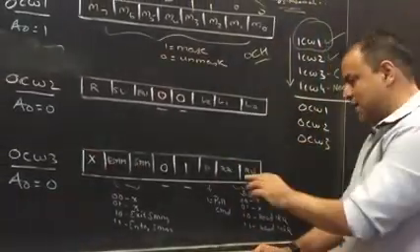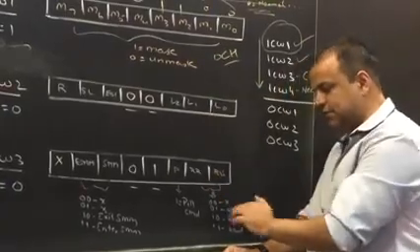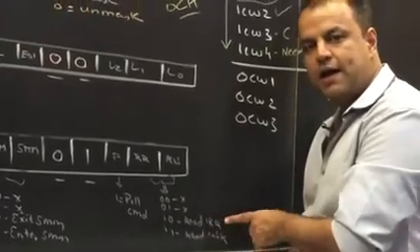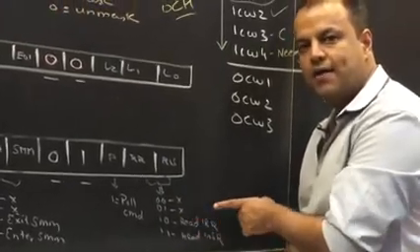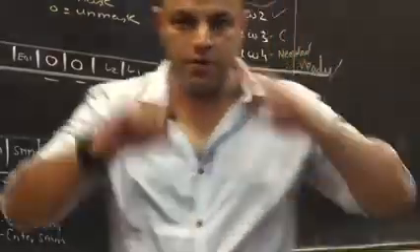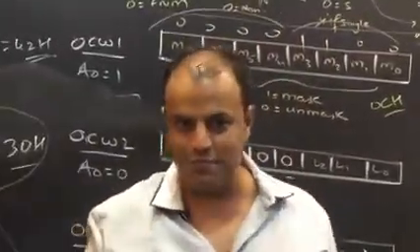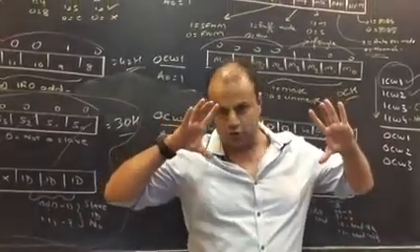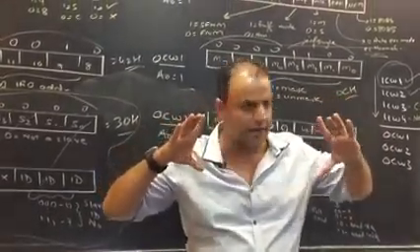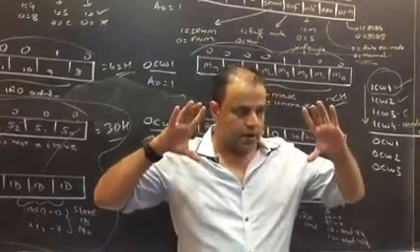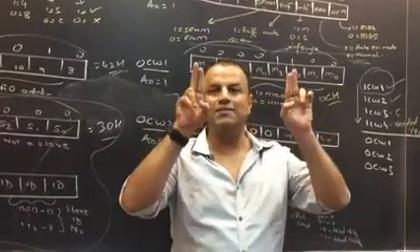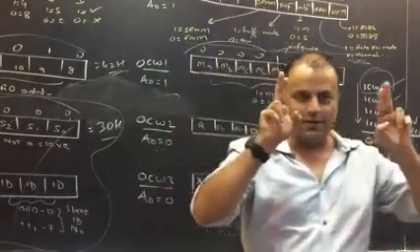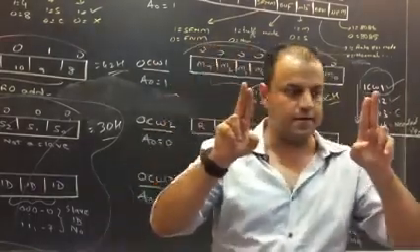Are you clear? RR and RIS. 0 0 and 0 1, nothing will happen. 1 0 and 1 1: read IRR, read INSR. I repeat, read IRR, read INSR. Do you remember in the architecture of 8259 there was an IRR and there was an INSR? I'm sure you remember that. That I'm not asking. If you have a very good memory, right above these two registers there were two buses going up. Do you remember that? That's my question. If you remember that, I'm very happy. That means you have either seen that video many times or at least you practice the diagram.